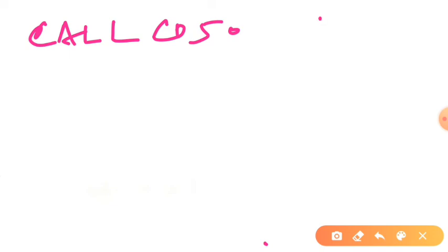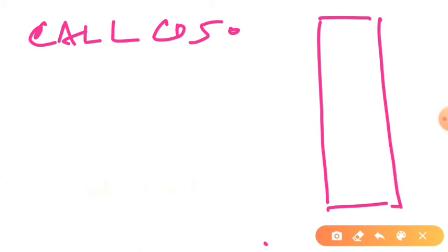Now let us also understand how to write this instruction in memory. We have the memory IC, obviously a RAM memory. In the program memory we write the instruction. Let us suppose the first instruction of our program memory is itself the call instruction, and our starting memory address, you know, is C000.